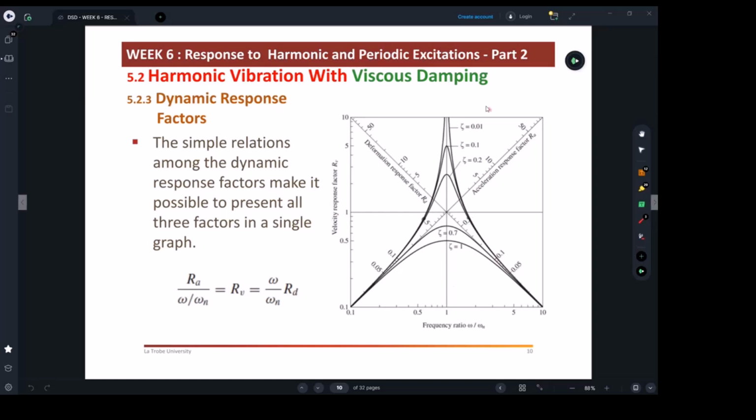So what we do, we go and read those manuals from the accelerometers, which will typically give you such graphs. Where we use these kind of graphs is usually when we purchase some dynamic measuring tools, or if you're like the traffic engineers who are going to be assessing the vibration for a bridge, they usually work with those charts because the equipment they use is defined with such charts.